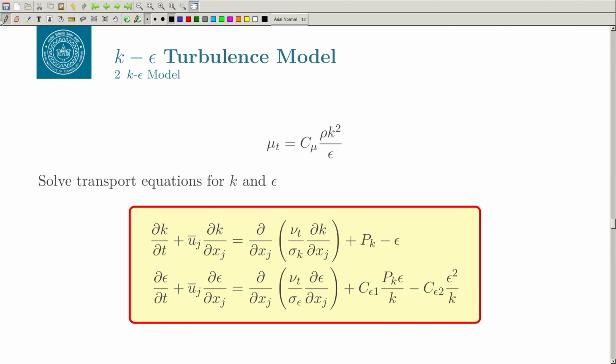And then we saw that we do not have any way to basically derive the equation for the dissipation, or dissipation rate. So what we did, we followed the different terms. Most of the equations that we see, whether it is mass conservation, momentum conservation, or energy conservation, have these terms available: the temporal term, advection term, and then the production term and the diffusion term. So, we use those terms and derive the transport equation for epsilon, which is the dissipation rate.